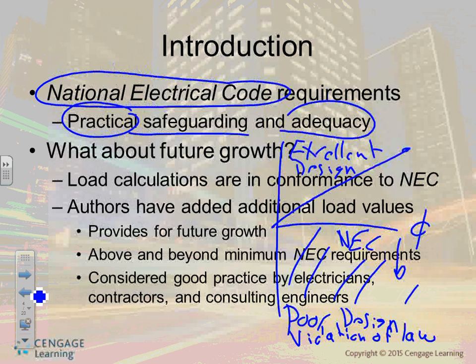So if you burn the building and they bring somebody like Chad, pay him $150 an hour to go to court as an expert witness, I hope he didn't use 220.12, right? He used 2 volt-amps per square foot instead of 3. And the judge, I refer it to the judge, and guess what? I become the star, and you go to jail. So this is where, if you go below the NEC code book, you are in violation of the law.